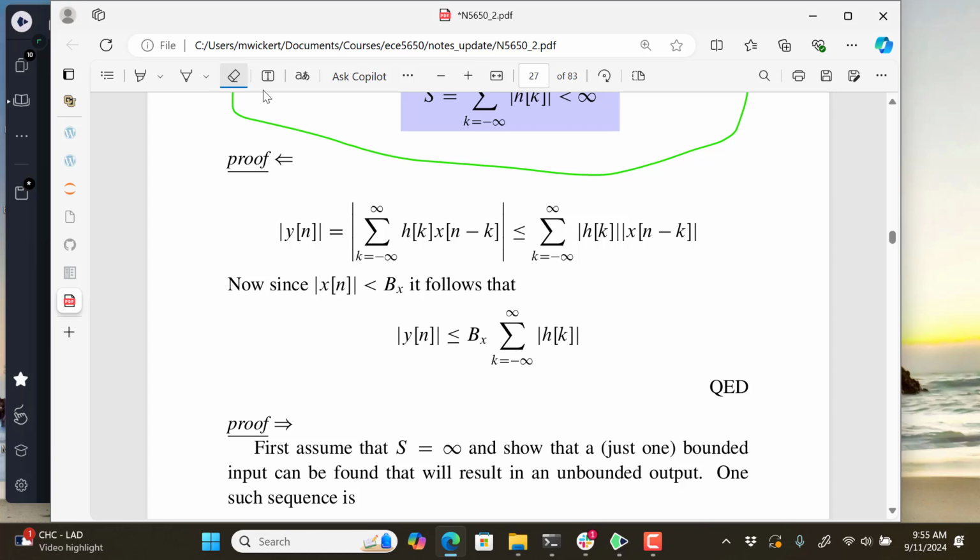If you want to think about why this works, it's kind of like visualizing what is the amount of gain that this system is applying to the input. And because it's doing the sum of the absolute values, it's looking at the worst case scenario. So if the system had spikes in the impulse response, which were two 1s plus and two 1s that were negative, you'd say, oh, that's going to average to 0 at the output always.